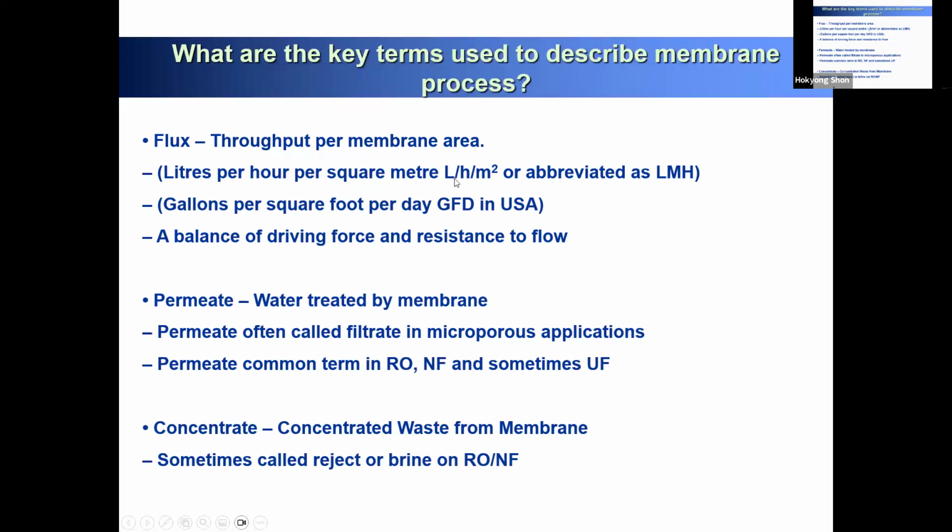Let's say this is one element. One element contains around 40 to 50 square meters of membrane surface area. So we have 50 square meters of membrane. I push it through for 1 hour. So how much water is produced? So you can design your membrane surface area. Okay, you pressurize for 1 hour, how much water is desalinated? You can calculate for one element.